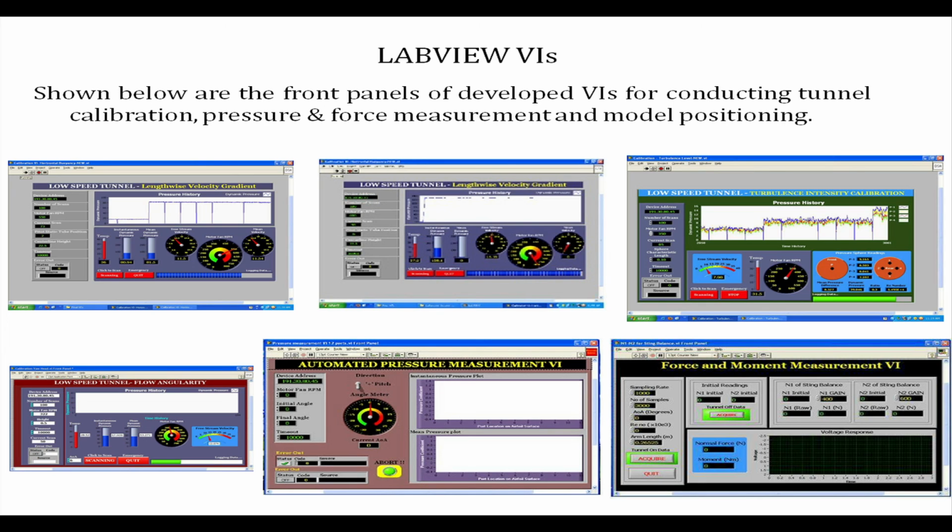Only thing that you have to make sure is that your sensors are doing fine, the hardware, which means the whole tunnel along with the models inserted inside, all the mechanical linkages, everything is doing fine, the electrical connections are fine, and your data is getting streamed properly. So, once you are very sure about this whole setup, there is no reason why you need to worry more.